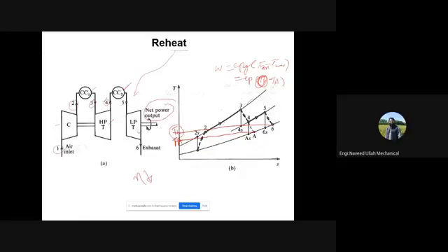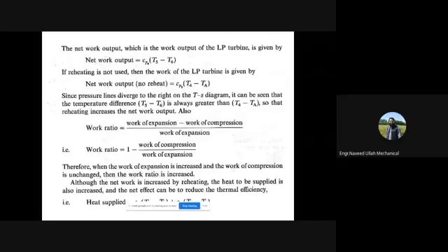मतलब ये है कि you are losing the exhaust that is having more temperature than this one. You basically lose in case of heat. Yes, you have the work of the turbine, at the same time you are losing more heat, and that loss of heat is basically the reason for this efficiency decrement, ठीक है। तो अगेन जो बात मैंने आपको बताई थी कि if you are using reheater or intercooler, so you can increase the work ratio, but at the same time the efficiency will decrease. Now यही एक्सप्लेन किया जो मैंने आपको बताई है, TA minus T6 क्या है खुद से फिर देख लें.